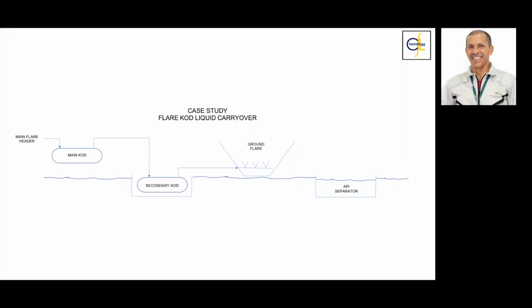However, the problem was with this system in particular, because they have one emergency in the refinery plants, and when this peak gas flow rate went into that knockout drum, this secondary knockout drum is very small compared to this. So they have, let's say, liquid there burning.